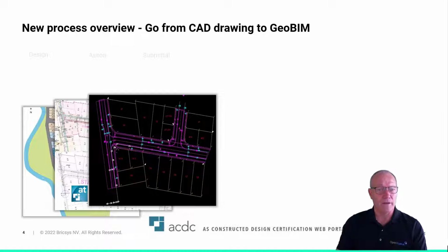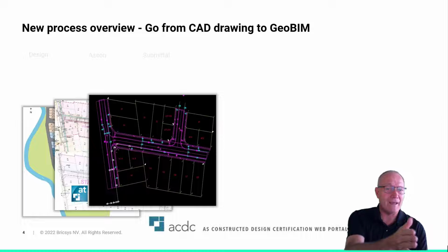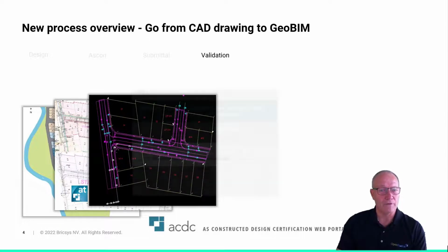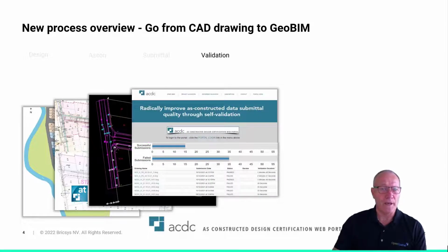What we're doing there is checking: did you fill in depth? Did you add number of turns? Have we got the direction of turns? Is it above ground, below ground? These would all be typical attributes, and in this workflow they would need to be captured at the end of the day. So what we're doing is putting that at the beginning of the cycle, which makes sense because that is survey accurate and sufficient for construction data, and so it should really flow downstream from there, rather than the old paper approach where you get PDFs and then somebody has to go and either resurvey or recapture that data.